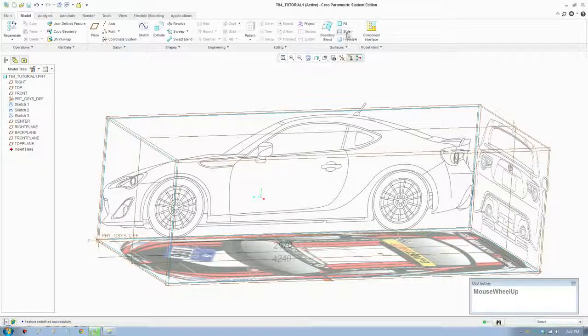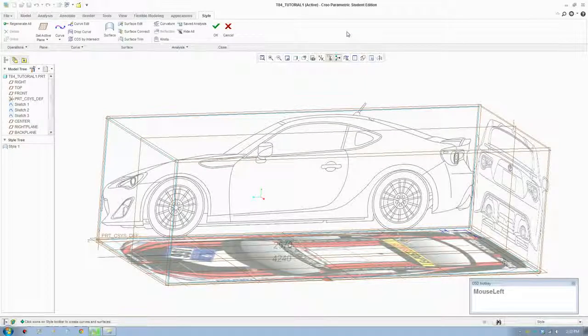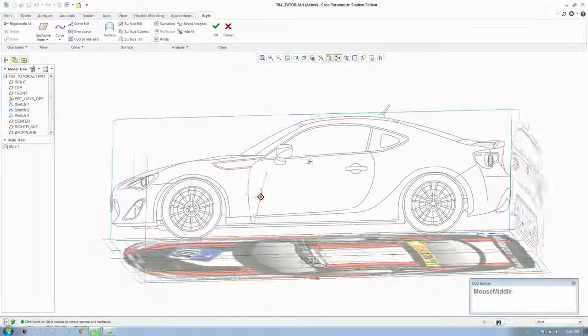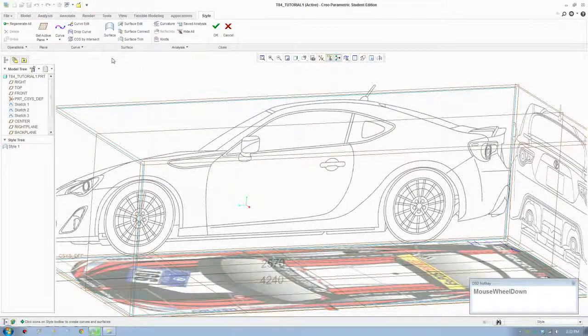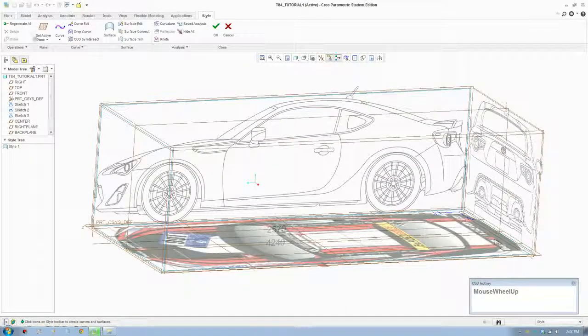So basically this style tool here lets you create surfaces, complicated surfaces. There's freestyle. Freestyle is more for basic form like a bottle, but to draw a car, we're going to use this tool here to build accurate, organic and complicated forms. So we're going to start with the roof, which there's a regenerate button. Generally, when you make a complicated model, you need to regenerate if you delete the curve or there is any problem. Set plane, just set the plane that we're going to draw on.